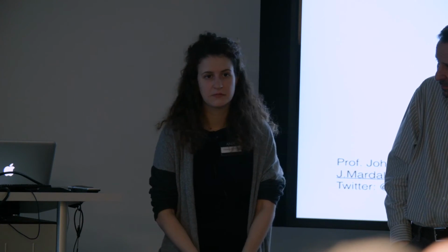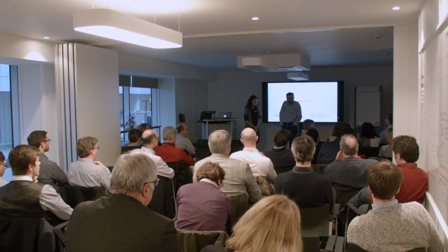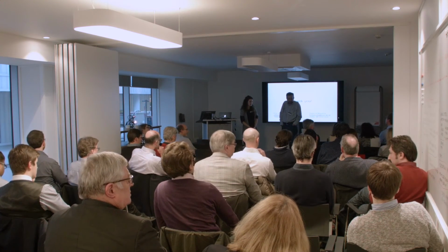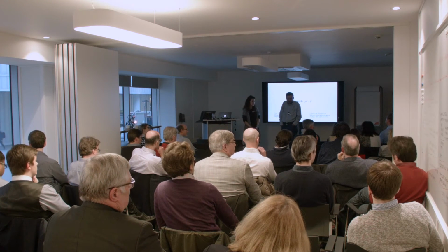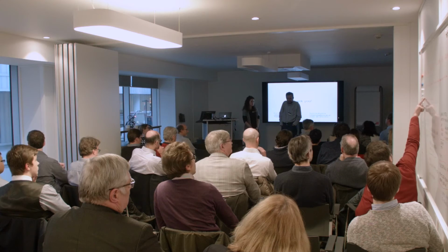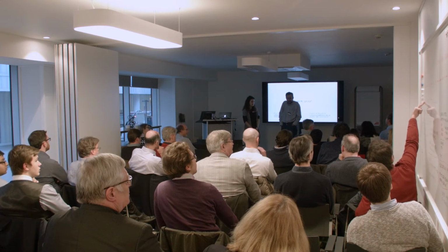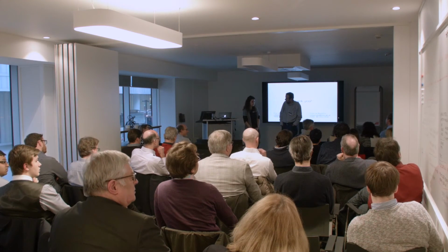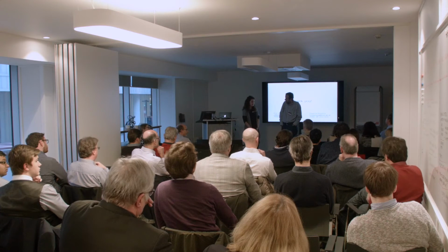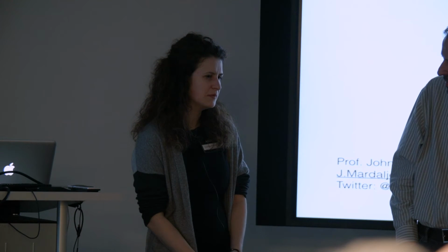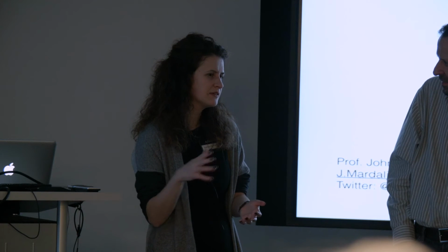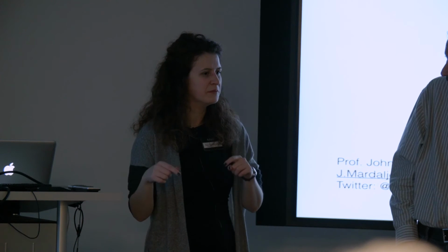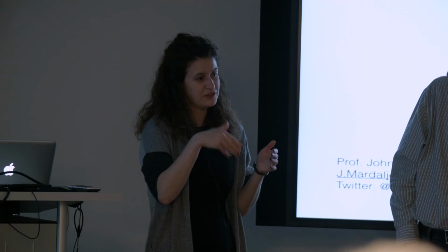Have you really encountered any problems with the way DaySim interpolates the weather file, which you use from any source? That's something I've experienced. When it does its time step, it interprets the weather file in its own way, and I've experienced some problems there. Have you had that? I didn't have a problem exactly, but I know that it's using a stochastic interpolation, so not linear. It's giving a randomness to the intermediate steps.